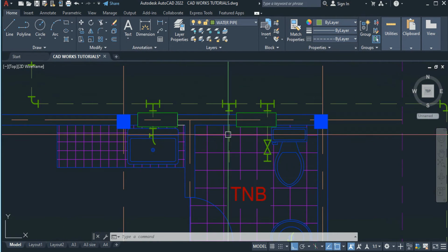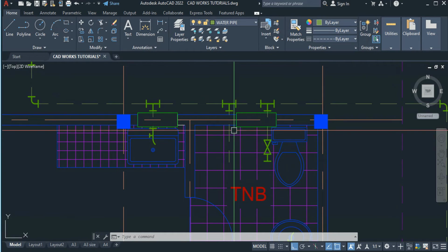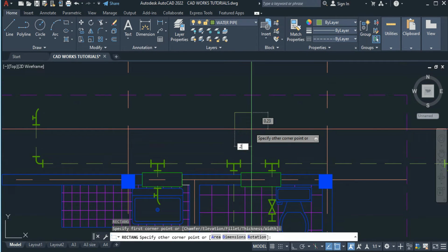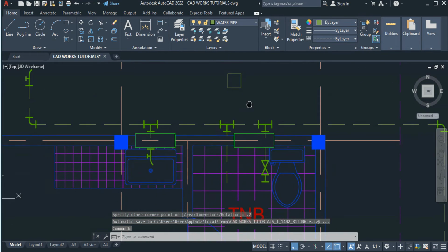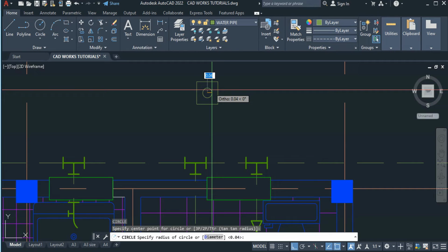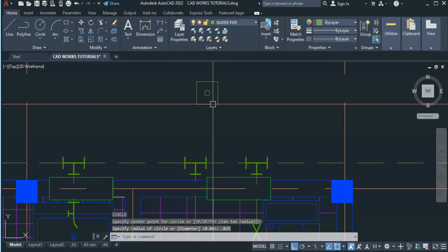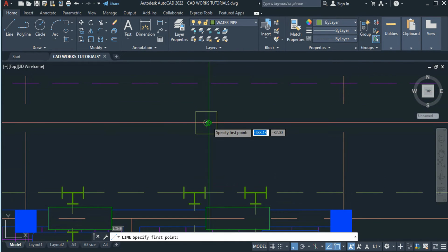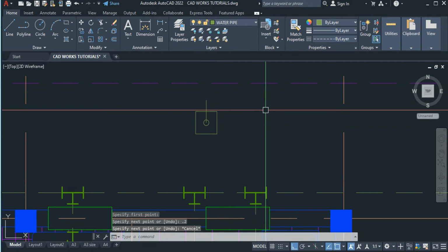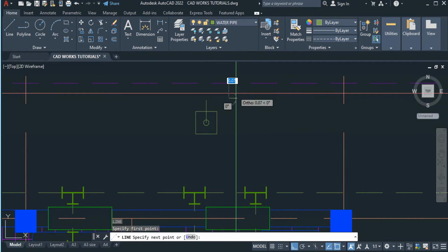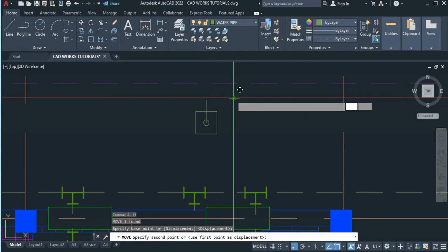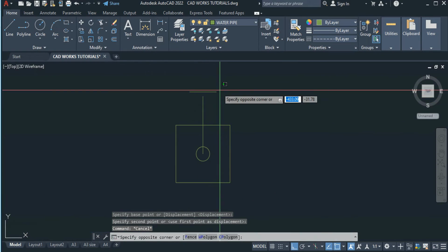So after none, we have to concentrate on the last drawing here. So I'm going to create a rectangular command here, then 0.2 tab 0.2. So in other words, this is the shower head. Okay, so 0.025, and then I'm going to create a line here of 0.2, then create a line here of 0.1, move this object to complete the drawing of the shower head.